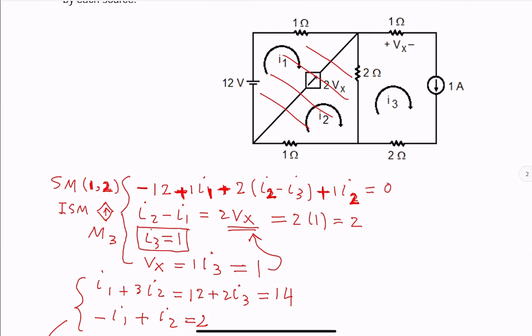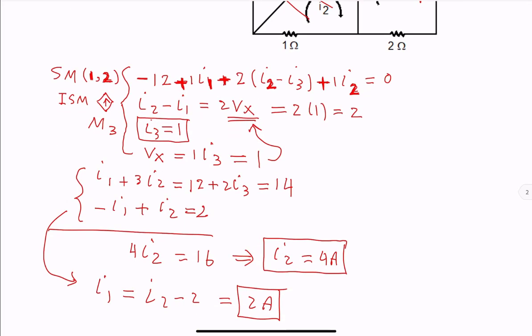Let us look at the current source on the right hand side. For that, if we use V1 and multiply that by 1, that gives us the supplied power directly. And to find V1, we can look at third mesh. V1 is summation of voltage drops across the 2 ohm at the bottom, 2 ohm on the left, and 1 ohm on the top.